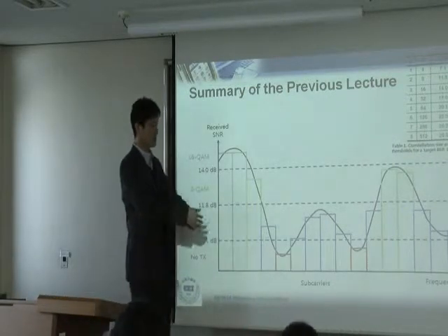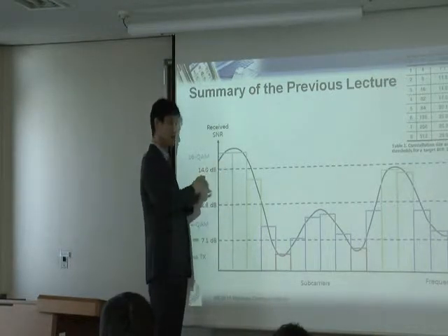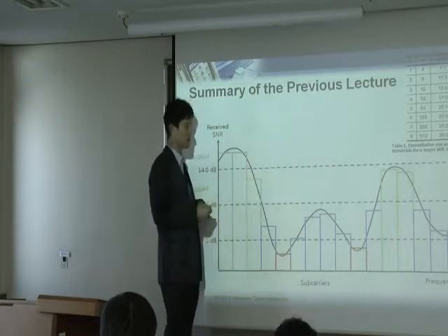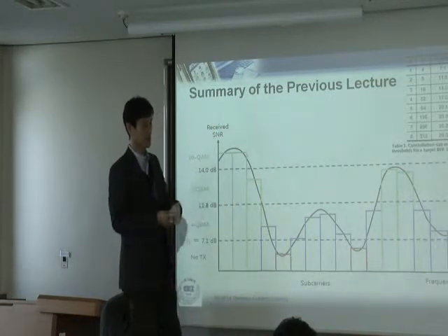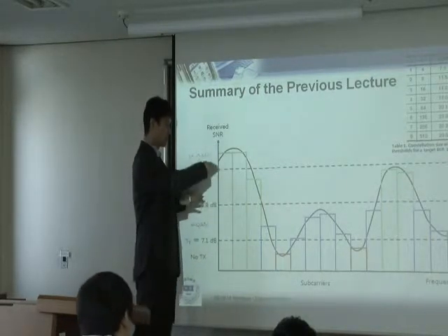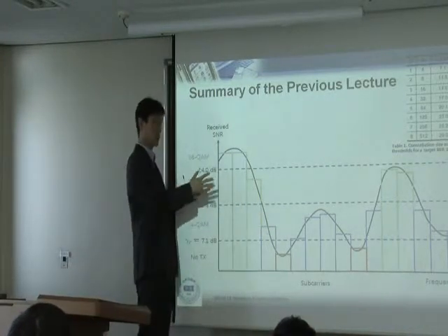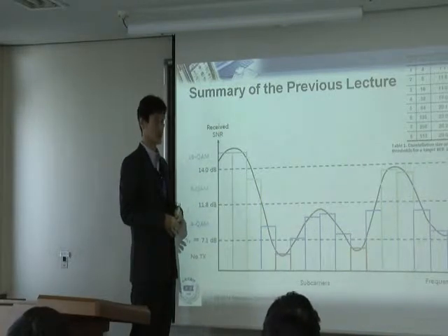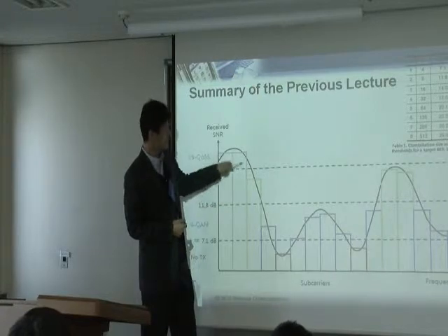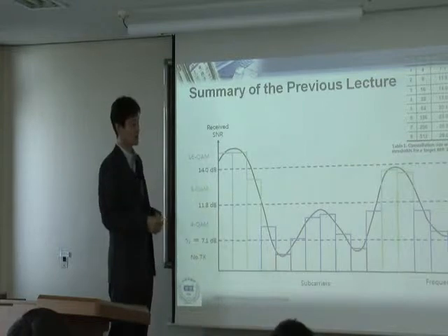Okay, so earlier in the picture we talked about that you can use a different modulation based on the time variation of the channel. The same thing can be done in the frequency domain. This is the frequency domain, and when the time domain changes, the frequency response also changes. So this is just one snapshot at one instant in time, and depending on the subcarrier, you have a different channel quality. So this is a transfer function, right? The frequency response of the channel.